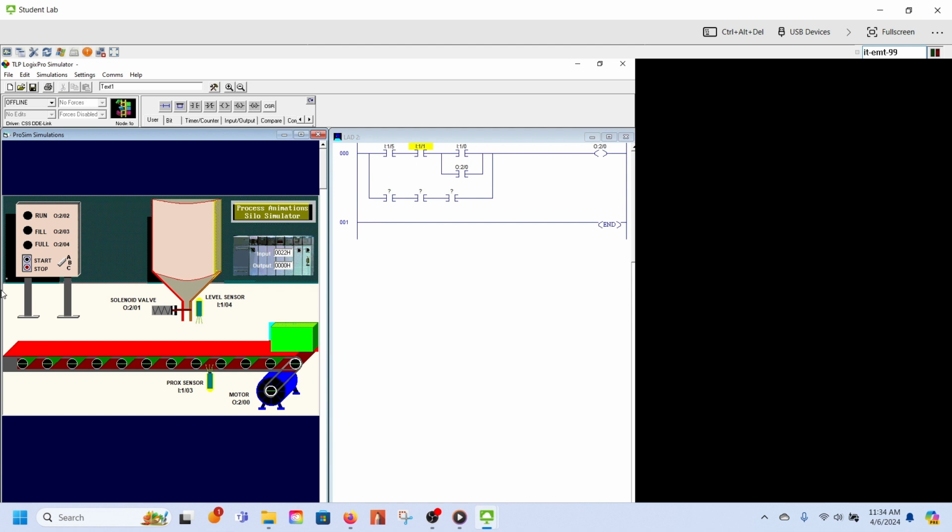So, we can grab our selector button here and add it here. We'll just go ahead and grab our stop button here and place it down here, and same thing here, our start button. You can grab it from either location. These were just closer, so that's why we did it that way.